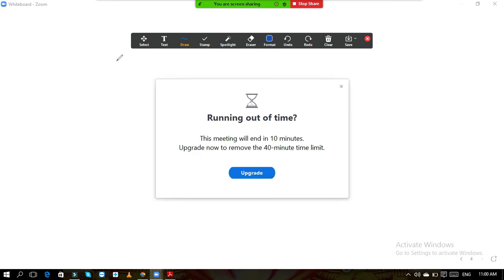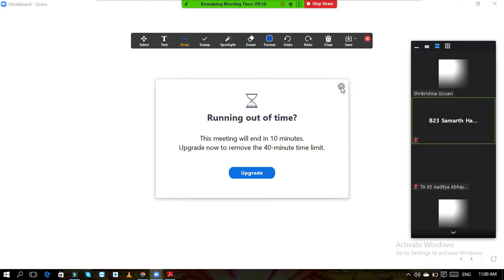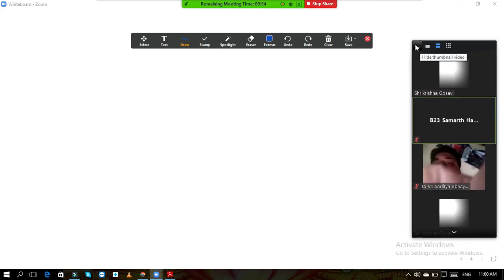again there is one shortcut for L0. In IS code they told us that we need to calculate the L0 by using two clauses which are given, but you can skip those clauses as the L0 we can calculate by the formula which is width of support by 2 minus clear cover.